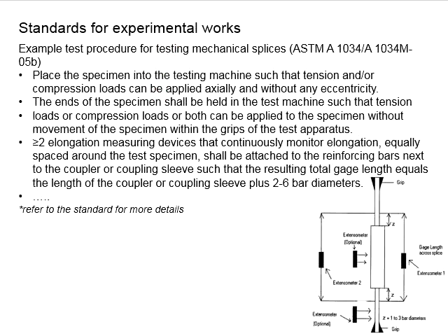That means you need the specimen to be properly gripped at the reinforcement bar here, such that the splice here is in static conditions, and when the grip moves up or down in the process of generating the tension and compressive force, there won't be any external force acting onto the splice.